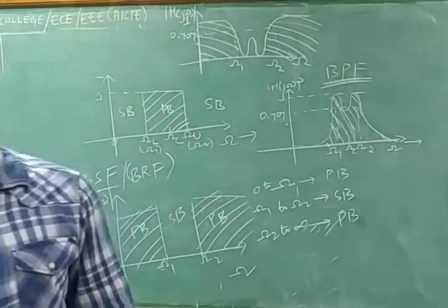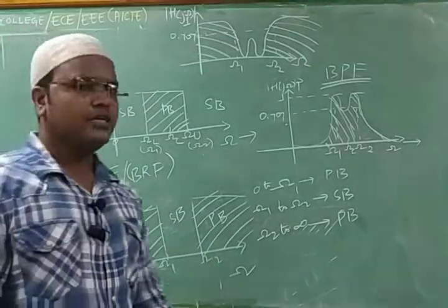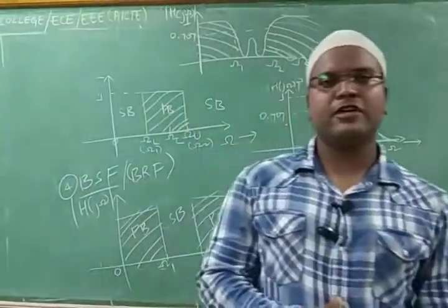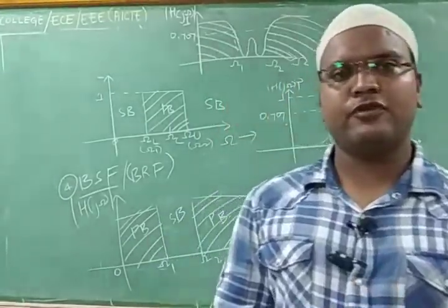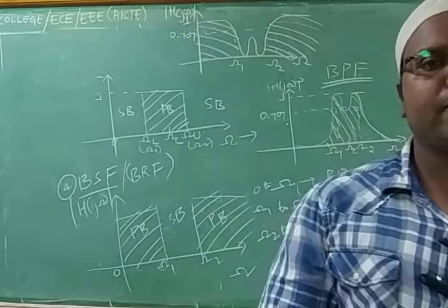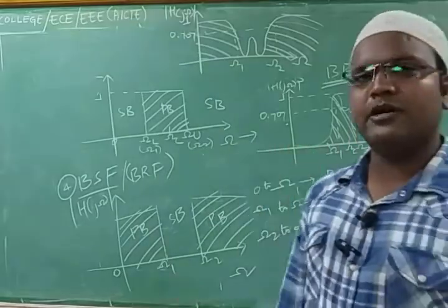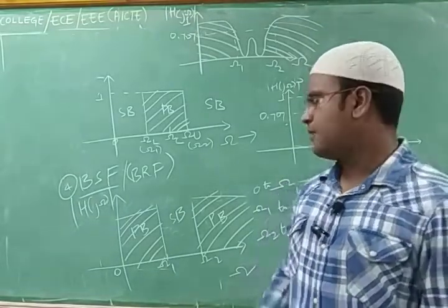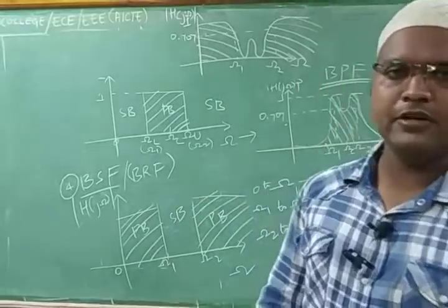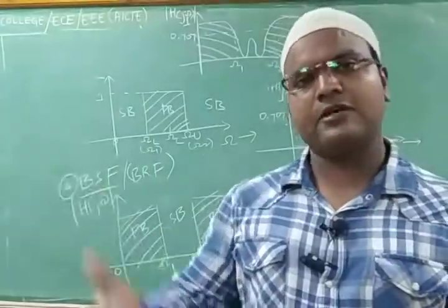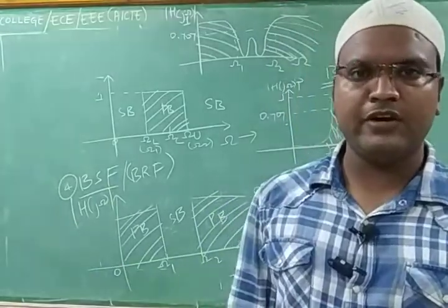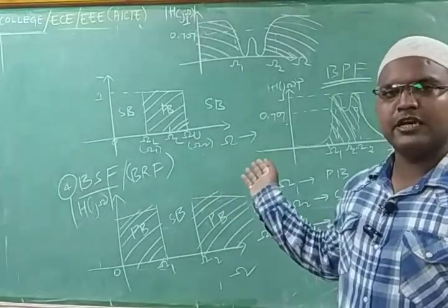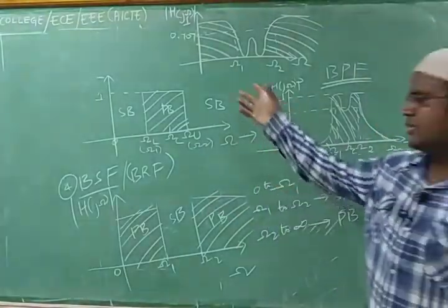These 4 types of filters are mostly used in IIR, that is, infinite impulse response filters. In that, we use these 4 types of filters, and we want to solve problems related to Butterworth approximation. There is a technique to find the transfer functions, converting the s domain into the z domain. We have taken the steps and, using those steps, we find the particular functions. In the same way, using Butterworth approximation techniques, we can find the transfer function for all these 4 types of filters.